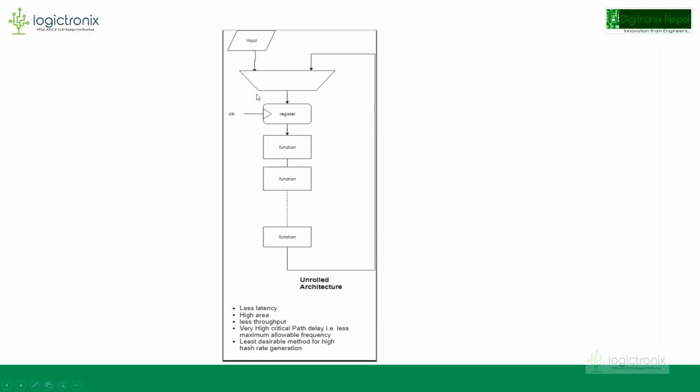The advantage of this design is that your latency will be a lot less. Like if you give two functions in Keccak, then instead of 24, you get output in 12 cycles, right? So you are likely to get higher throughput in some scenarios if a function has a less critical path. But what happens if you just stack this function over and over again?